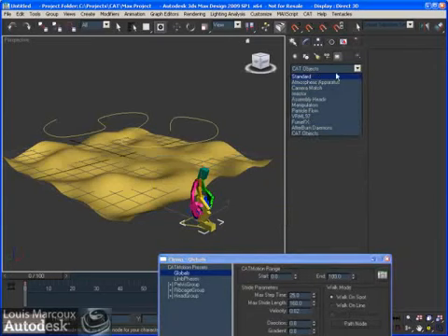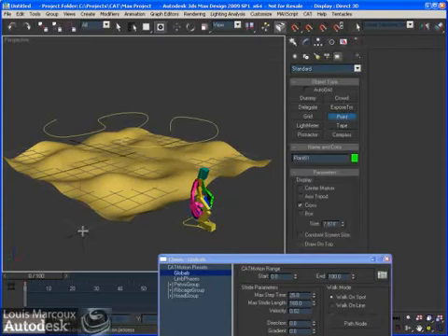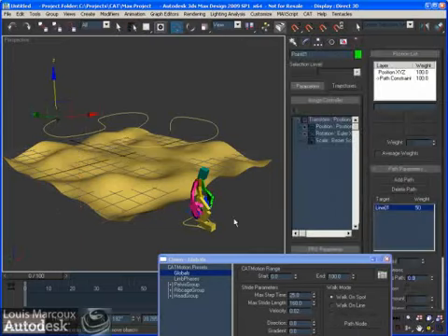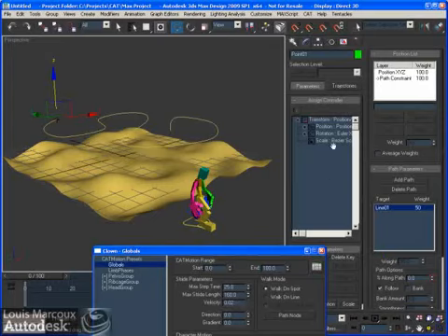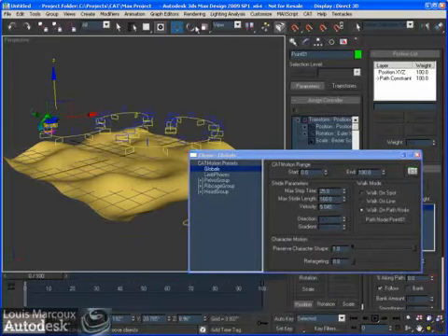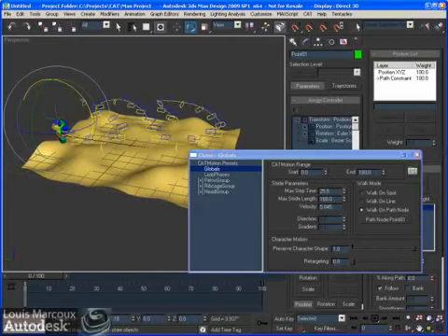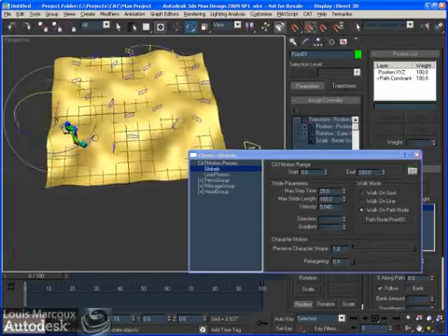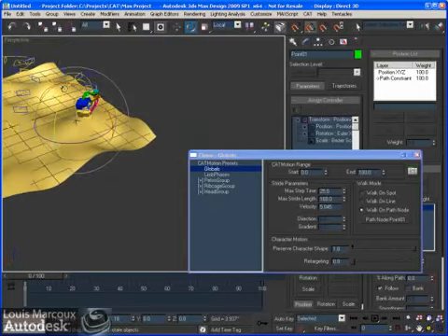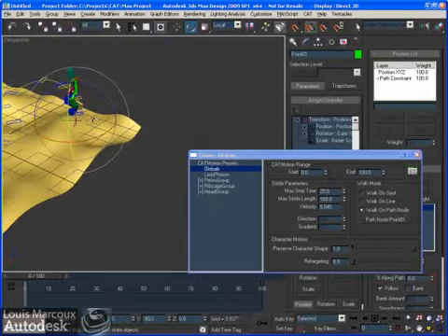I started from a blank screen because I realized that I forgot something. So let's go into the standard helper, just put a point helper. Not too big. Here we go, and just animation constraint, path constraint, follow that path, and of course follow. So now I'm ready to grab this guy and say follow this path node, and I'm going to just rotate it in the right direction. Oops, 90 degrees, where's that guy? So 90 degrees local, 90 degrees up like that, and 90 degrees forward.